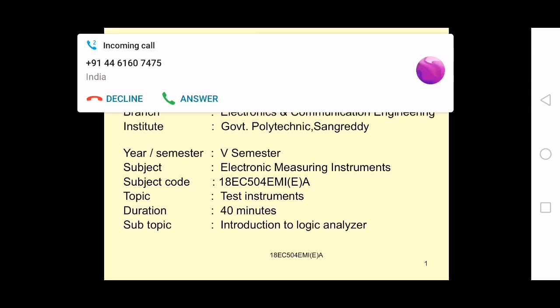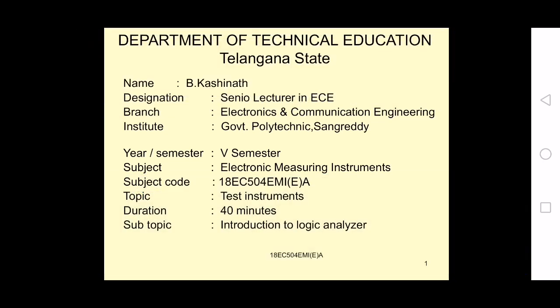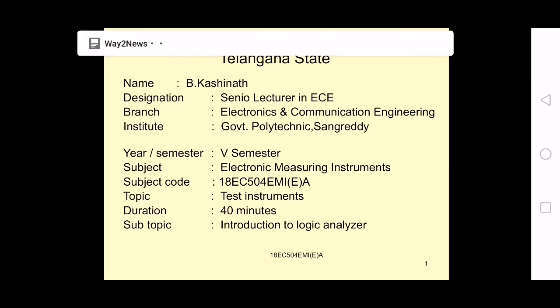So on the display you will have the frequency spectrum, that is, on the x-axis the frequency components and on the y-axis the amplitude, as vertical spikes with respect to frequency. That we call the frequency spectrum analyzer.